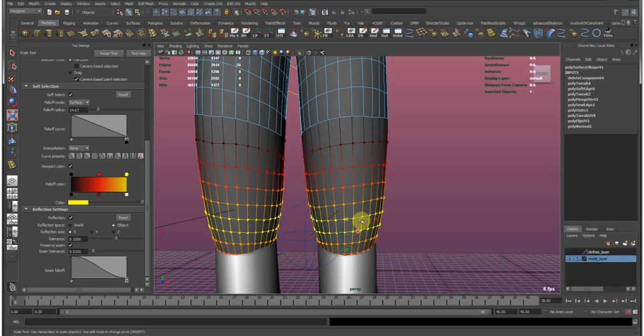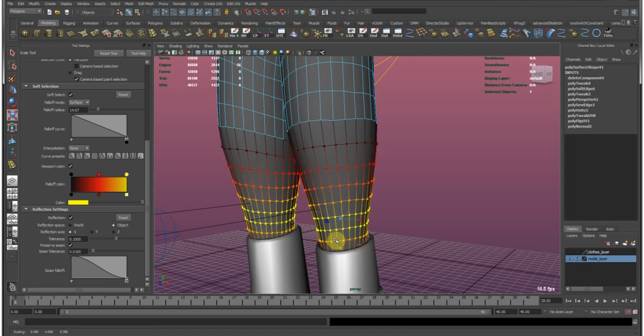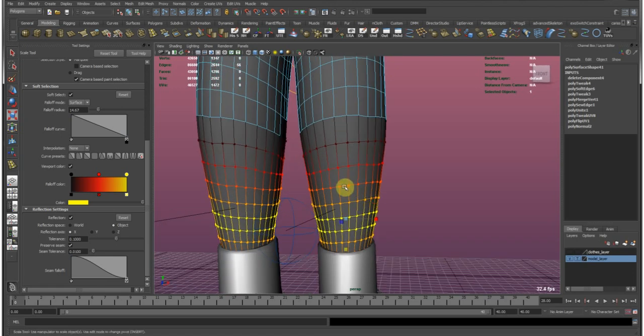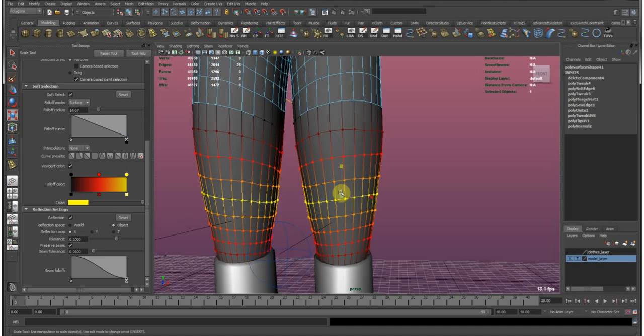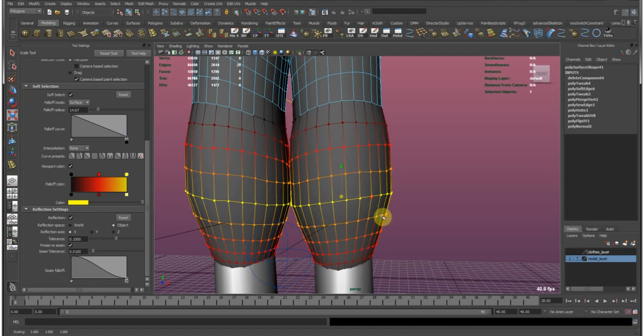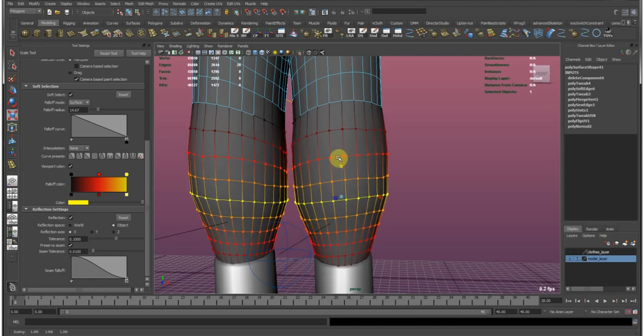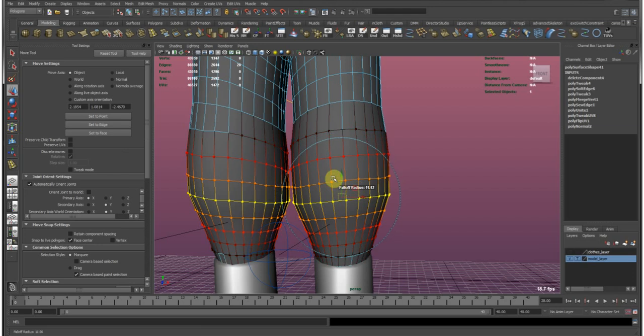How I can do this is there's a nice trick. When you control click the axis that you don't want to scale in and then scale, it'll scale every other axis but leave that axis untouched. So that I can scale in soft selection mode without having those upper and lower edge rings scale up and down. So I'm gonna undo this and control click and hold the Y axis to scale only in X and Z. This is the trick behind this.